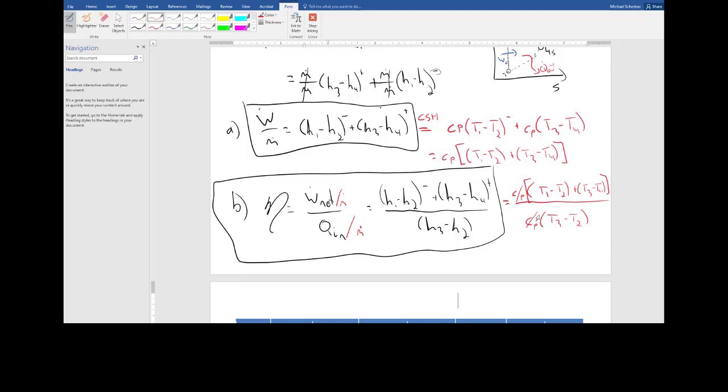And actually, even though it's an ideal gas problem, so my spidey sense is tingling, always use Kelvin or Rankine, it actually wouldn't matter in these particular problems because we're always talking about temperature differences, at least in these equations. But we'll see as we fix states that's not true. So I could answer this problem if I knew T1, T2, T3, and T4. The beautiful thing here is the textbook, or whoever wrote this problem, told me T1, T3. I just need T2 and T4.